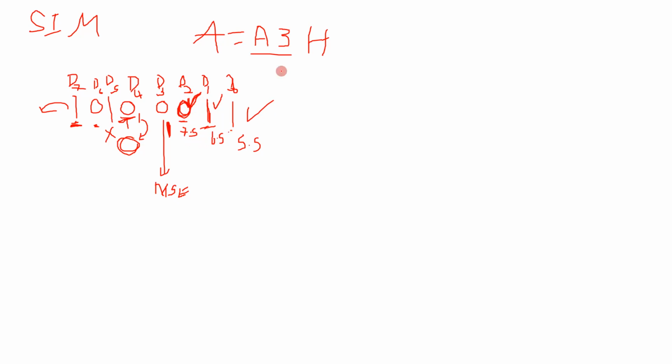So the programmer will decide the contents of the accumulator beforehand. Since this is 0, these bits have no meaning. This same instruction will not be used for masking or unmasking the interrupts. Even this instruction will not be used to serially output the data.